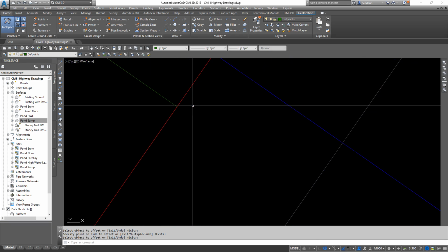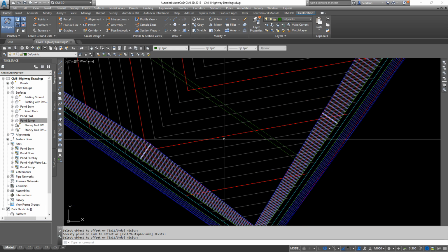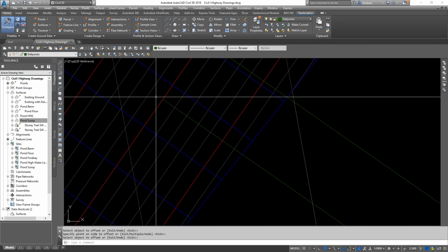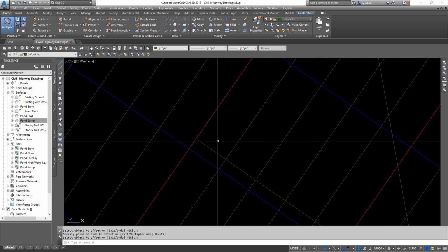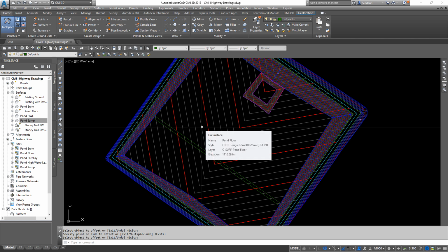So again, just make sure these 2 polylines are touching this red contour line, that's 1118. If you snap to the wrong contour line or get the wrong elevation, you're going to know it right away when we make a combined master surface.